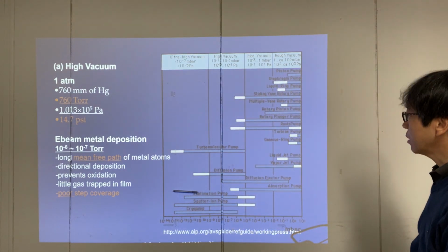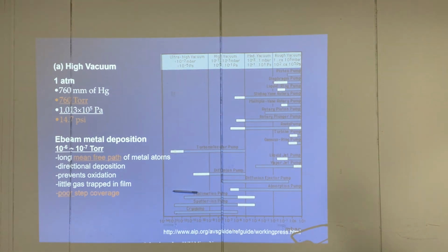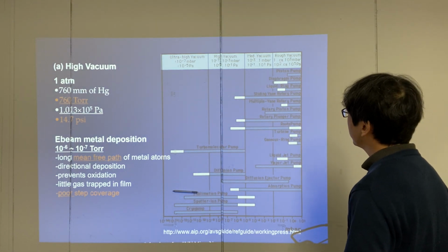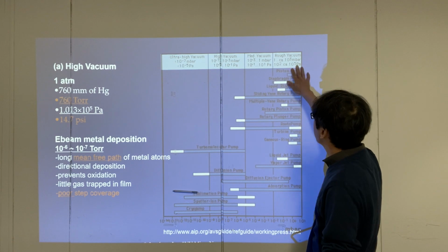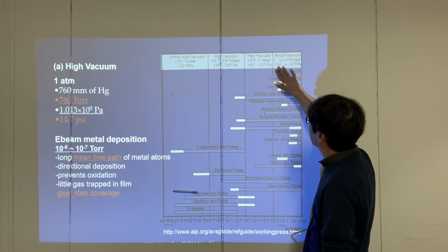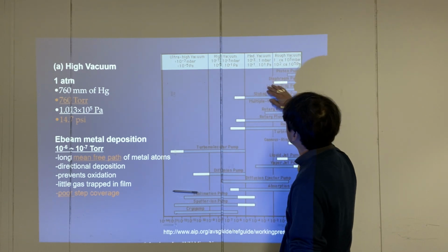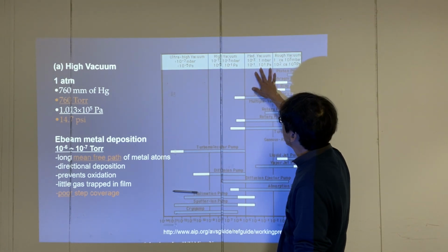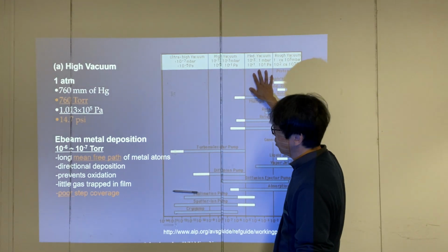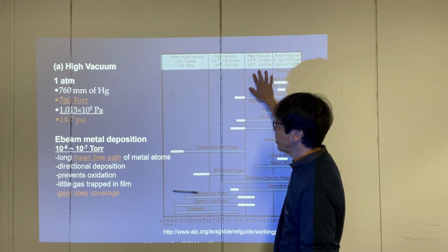All right. So these are the vacuum technology that can be used. It's not very highly visible. I'll give you guys the material. Well, depending on the vacuum range, we call this rough vacuum. It's gonna be 10 to the 5th Pascal down to 100 Pascal. And medium vacuum, and these are the vacuum that we are talking about for low pressure chemical vapor deposition.